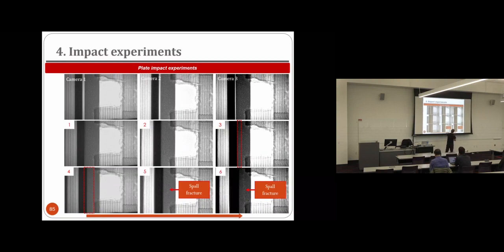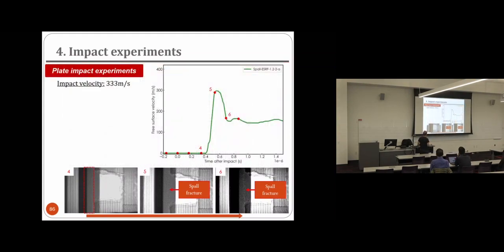Okay. So again, here with the presentation and everything the light is not perfect, but in the image after the processing you can see it very clearly. Here you have the spall fracture. And the cool thing is that we can relate the video recording with the signal. So we know exactly when a spall occurs. For instance, here is the incipient spall, which you can see a little bit clearly in this section that corresponds to the midsection of the specimen.